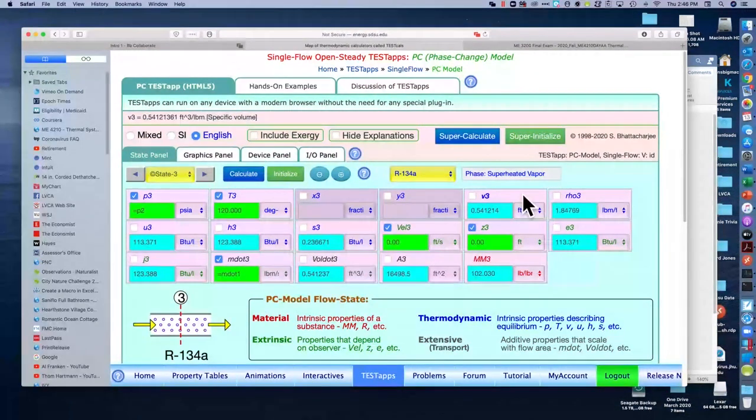The one that we're most interested in is the elevated enthalpy associated with that third state. We would compare that to the enthalpy of the isentropic compression of 115, and we compare both of those to the enthalpy of the incoming fluid. And so we have our three states.